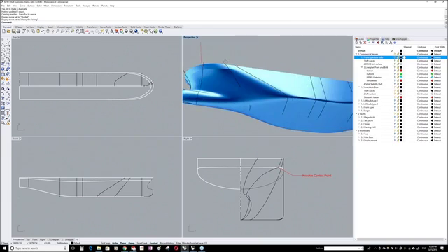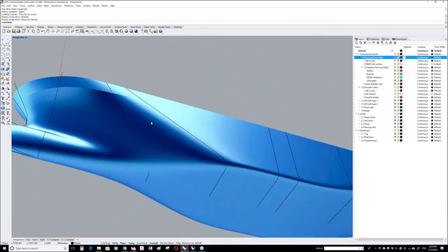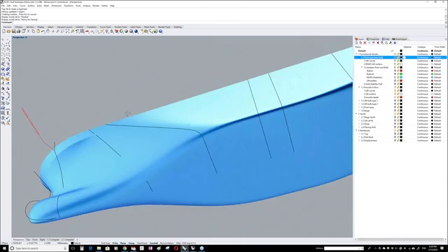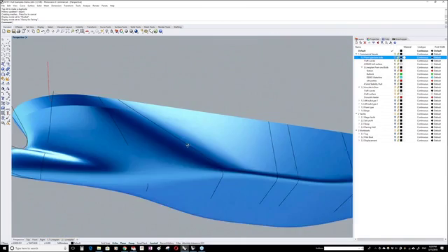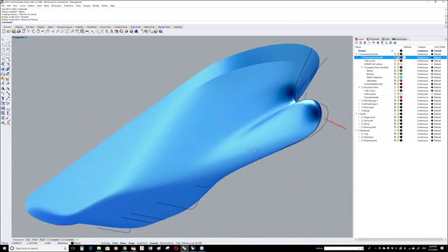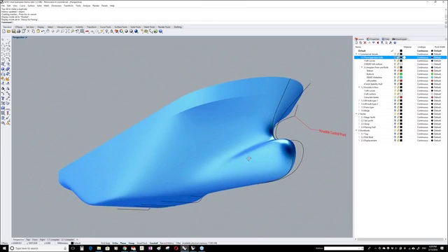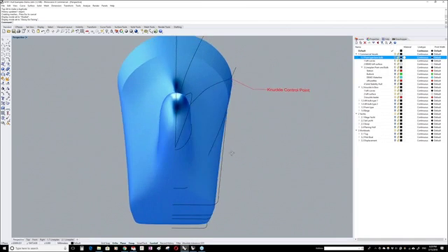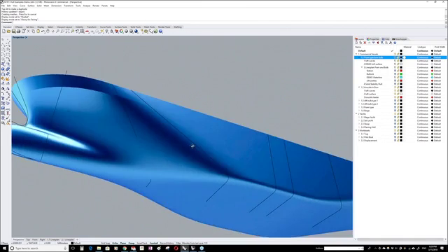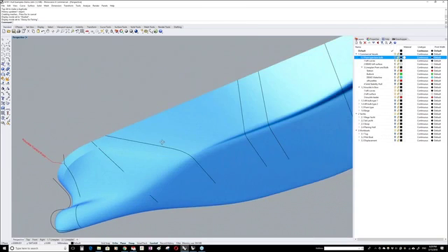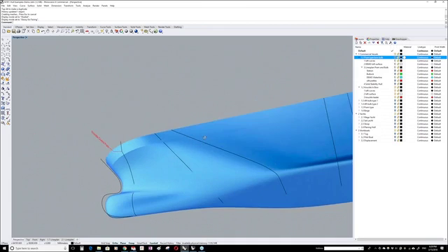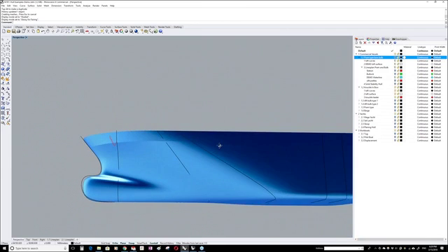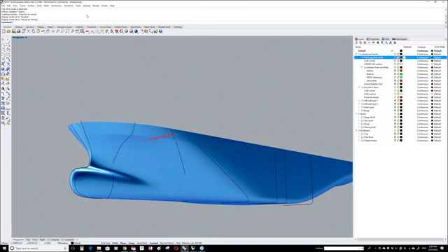So now people can see, if you zoom in and maybe make perspective full, yes, please. And now you see that the hard knuckle fades out into the midship. So, the position where that is, if you zoom in, please, yes. So now people can see where the knuckle fades out, and the position of the fading out you determine with loft curve positions or control point positions. So it is doable, but it takes your skills, how much control you have. So I hope that answers the question.